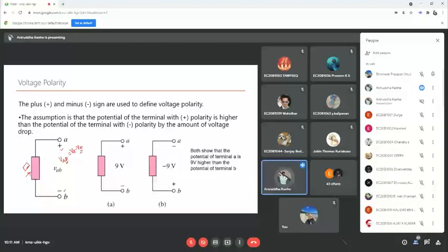This is the general convention of writing it. Whenever there is a voltage written as, let us say, XY, it always means VX minus VY. Don't consider VY minus VX. Don't try to have some new set of nomenclature for that. Just take it as it is, and then VA minus VB in this case